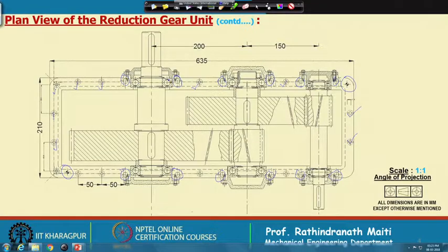And alternatively, some glue type materials also can be given, so that it will prevent it. There is a rare possibility that oil will leak through that and dust will go inside through this. And as you see this input and output, although it is not shown here, but I have shown that we can use the oil seal.